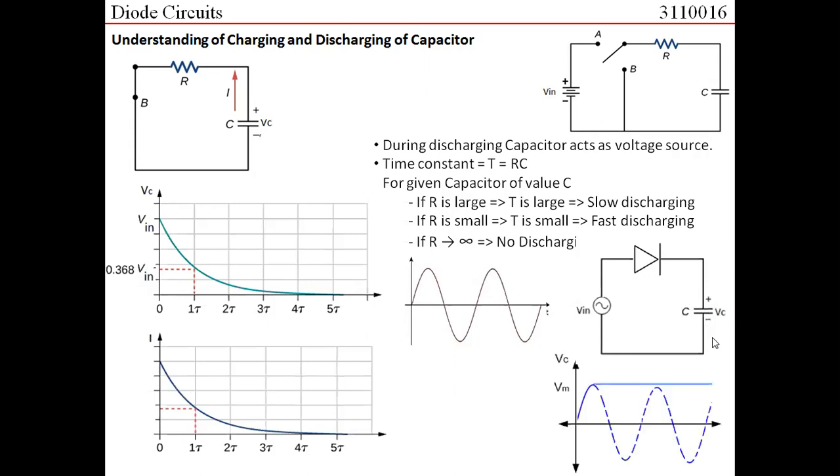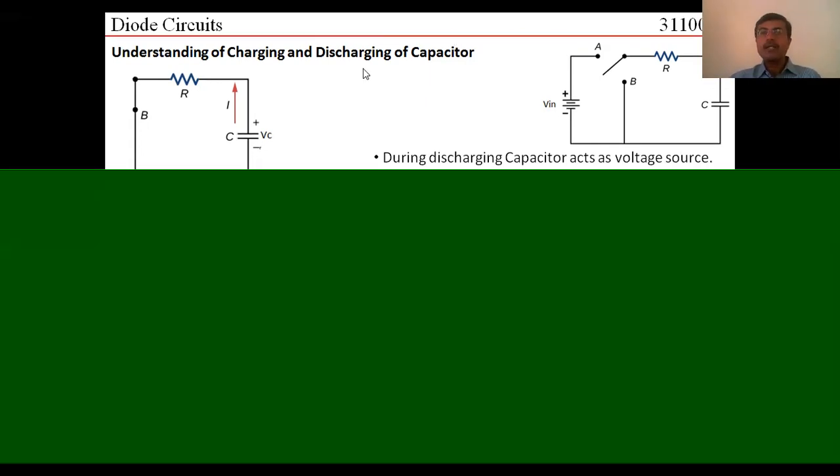So if we try to see, this would be the waveform of Vc. Initially, it would charge up to Vm along with the input voltage, and then it would maintain Vm constant, because after this the diode would never come into a forward bias state. This understanding would be quite useful in understanding clampers. Now let us try to study different examples of clampers.